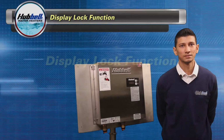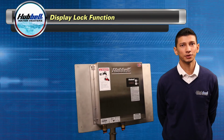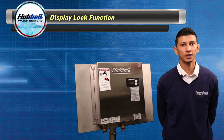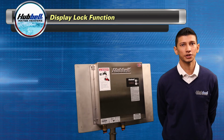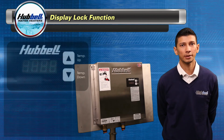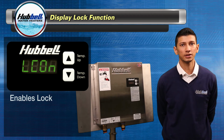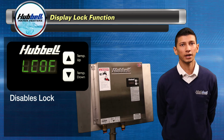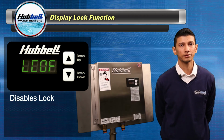The next parameter is used for the display lock function. This function allows the user to inhibit any changes to the set point in the configuration menu when enabled. You can enable this function by programming the parameter value for LCON and disable it by programming it for LCOF.